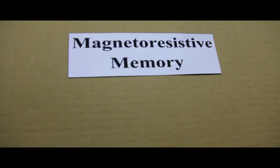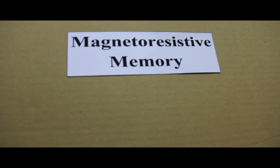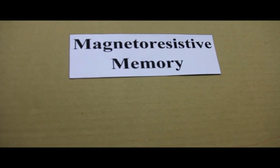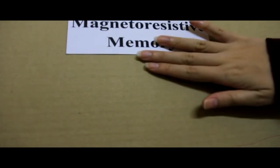Magnetoresistive random access memory, MRAM. Magnetoresistive random access memory based on magnetic tunnel junction bits is a promising scalable non-volatile memory that may have unlimited read and write endurance, high-speed read and write operations, and low power consumption.